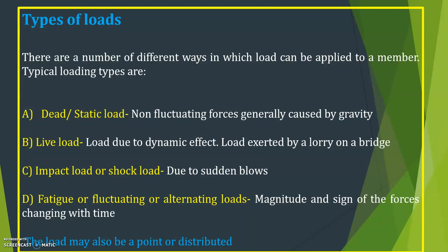If the spread is not at uniform rate, then it is said to be non-uniformly distributed load. For example, triangular or trapezoidal distributed load fall under this category. I think you must have studied about uniformly varying load, right? Triangular load. So this is about the loads, mainly point load, uniformly distributed load, uniformly varying loads.